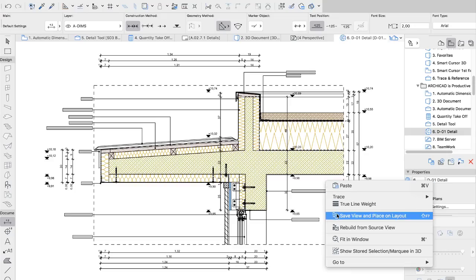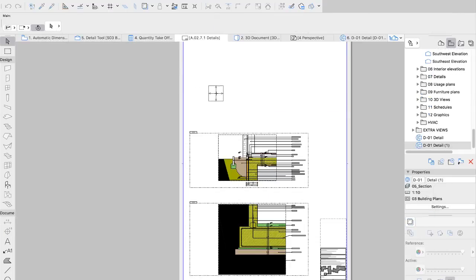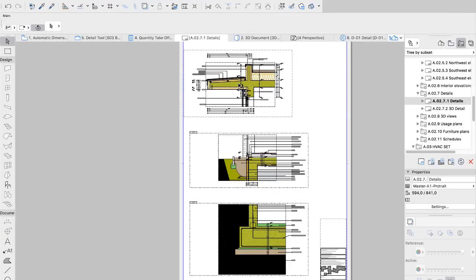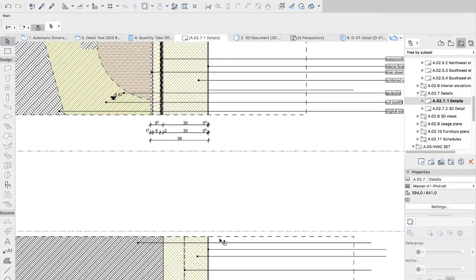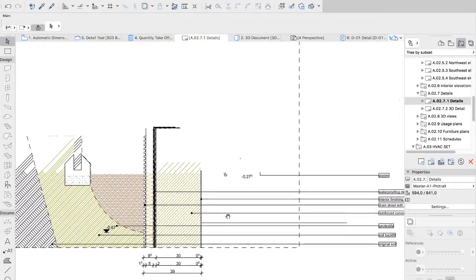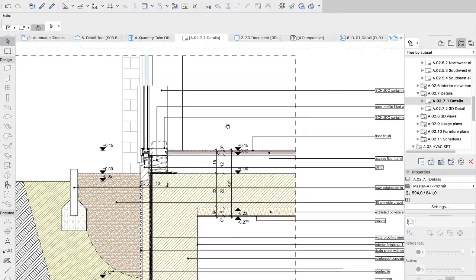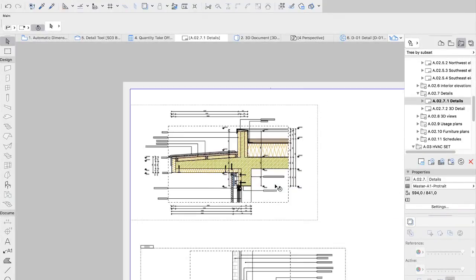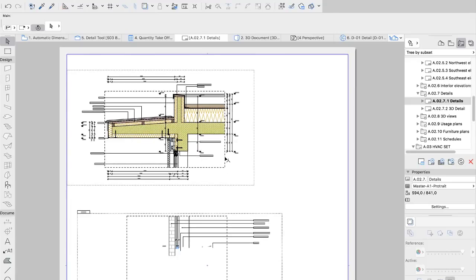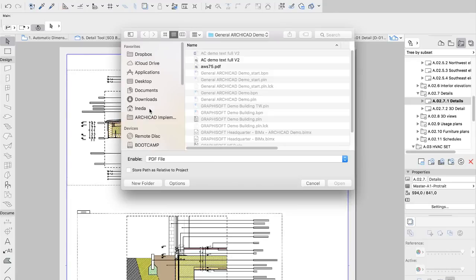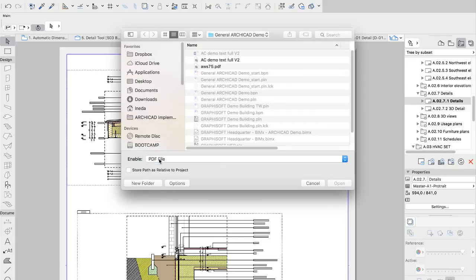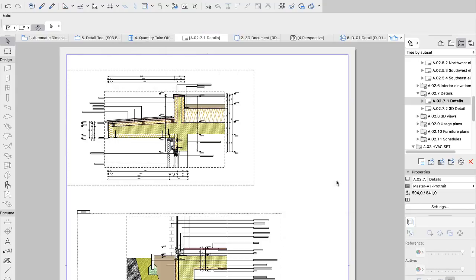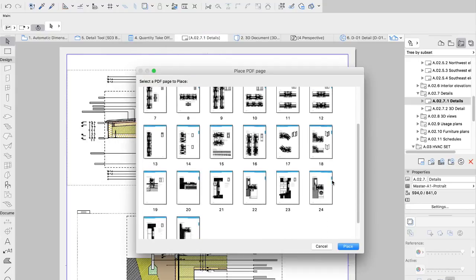When you have finalized the detail drawings, you can place them on predefined company standard layouts and arrange them with graphical methods. Note that these smart master layouts can manage automatic drawing numbering and naming. No need for tedious manual rework before publishing. You can easily incorporate any manufacturer's information within your documentation. Even PDF details can be placed on layouts.